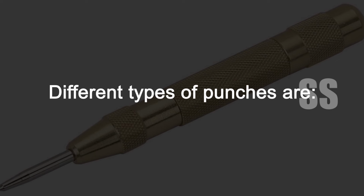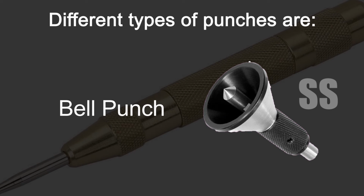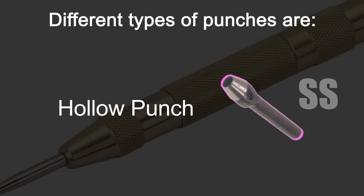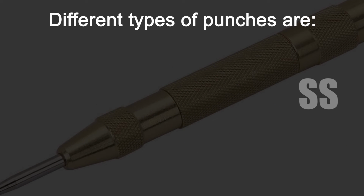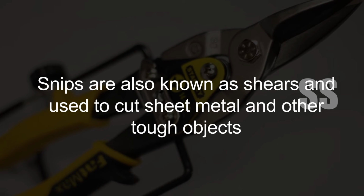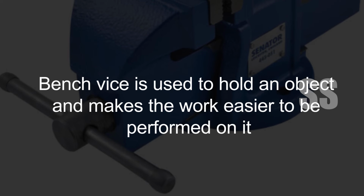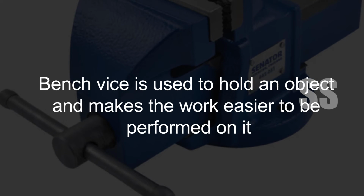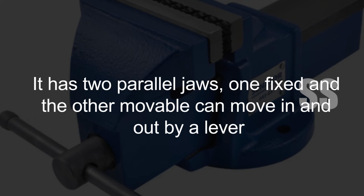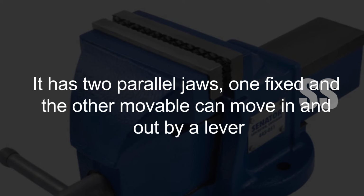Different types of punches are dot punch, prick punch, bell punch, hollow punch, double end punch, center punch, solid punch, pin punch. Snips are also known as shears and used to cut sheet metal and other tough objects. Bench vice is used to hold an object and make the work easier to be performed on it. It has two parallel jaws, one fixed and other movable, which can move in and out by a lever.